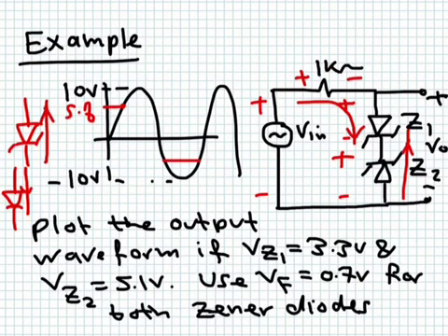So this is a typical example where you determine the region of operation and the circuit will determine the current for you. Actually, we can determine the current for any input voltage value. In the forward direction, if this branch is on, in the positive direction, the current is equal to Vin at any time minus 5.8 divided by 1K.